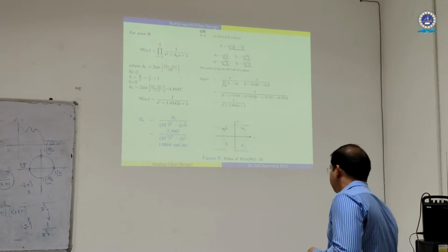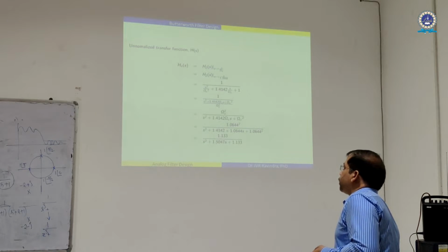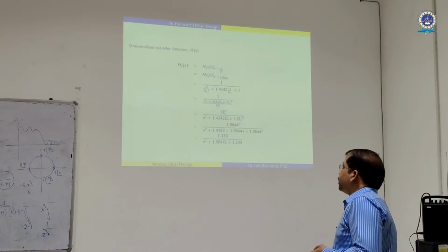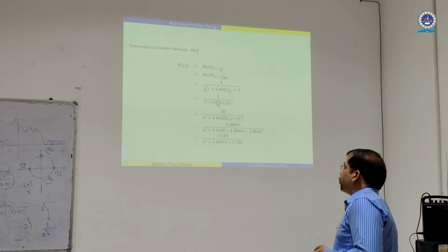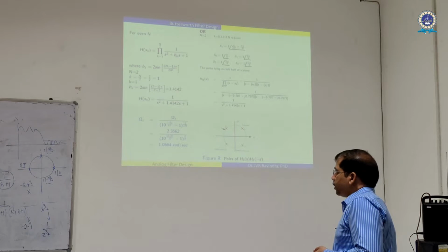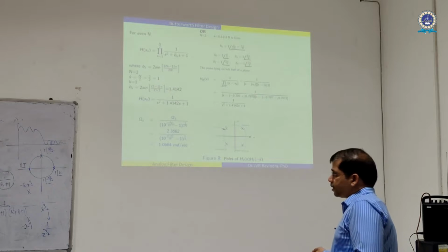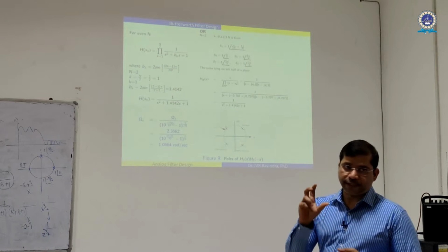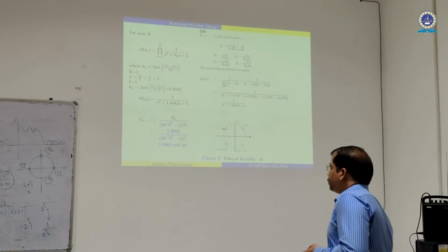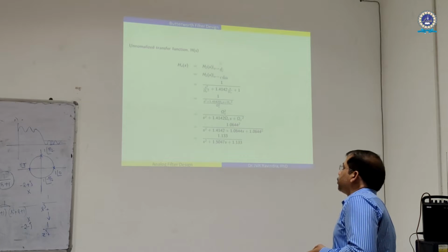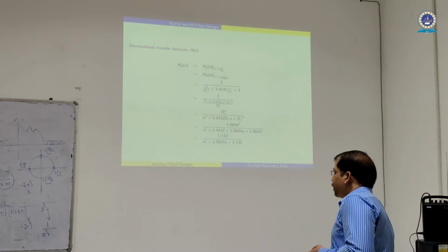So that's the reason we have to transform to the original characteristic. Therefore, s turns to s by omega c. This omega c calculation, if you look at it, what is the omega c? This is omega c, wherein you are using ks. What is this ks? It is there in the design constraints, and this n. All these values that you are using, you substitute here. Therefore, you get this transfer function.